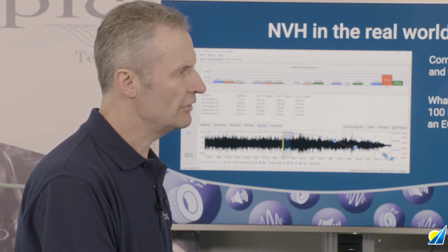On that point, if we look at the influence of the engine mounting, you could also use the accelerometer as a stethoscope, perhaps place the accelerometer on the engine, measure E2 values there, take them off the engine, mount them on the chassis, look at the comparison between the two. If that engine mounting is performing correctly, there should be adequate suppression of that vibration. I think when you think of how this was detected in a non-intrusive fashion with the accelerometer on the seat bolt, driver's seat frame, yes. It doesn't get any less intrusive than that.